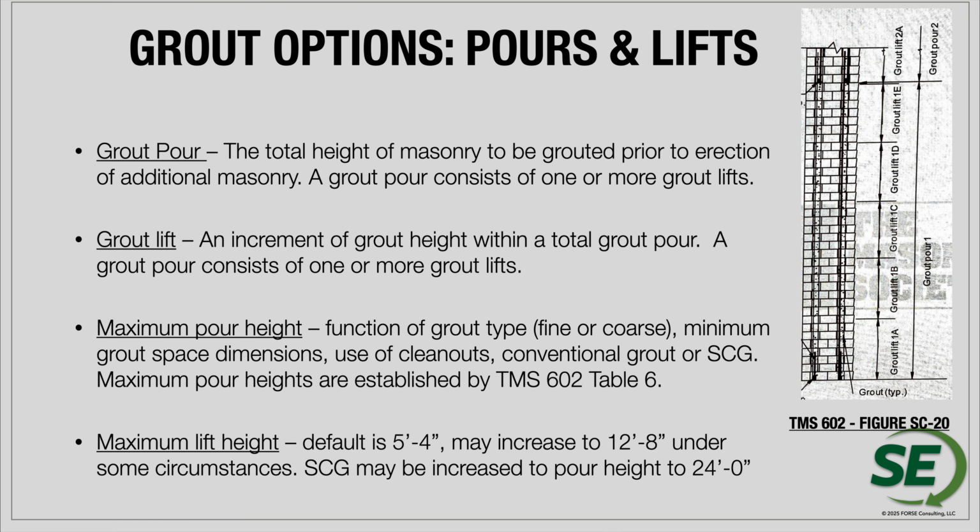Just one other thing to mention about a grout is understanding what the different pour heights and lift height options there are. Within the code, within the TMS 602, it gives contractors a very good guide for how to place grout depending on the size of cell, depending on height that they want to pour a grout lift, or actually have the grout lift within the grout pour is what I should say. And the diagram on the right does give us a really good illustration for what would define a grout pour height and what would define the different lift heights.